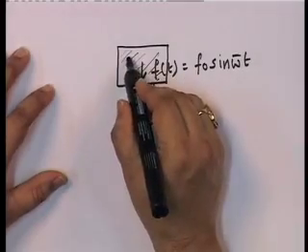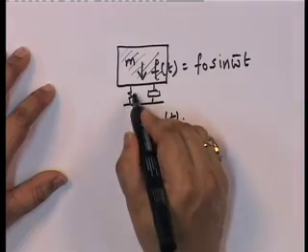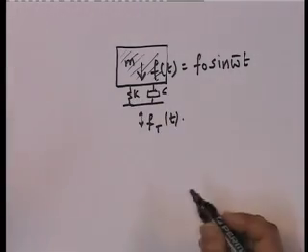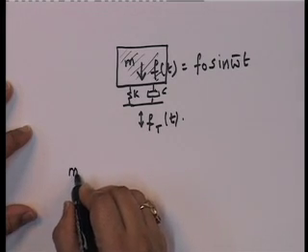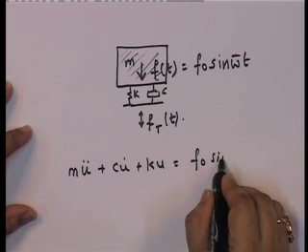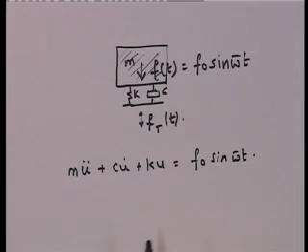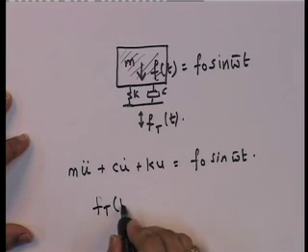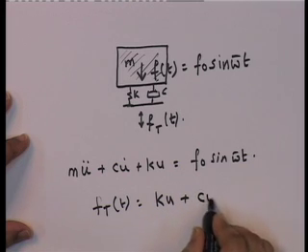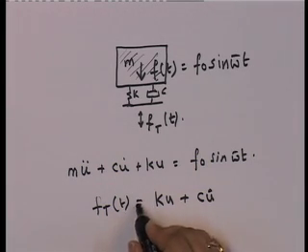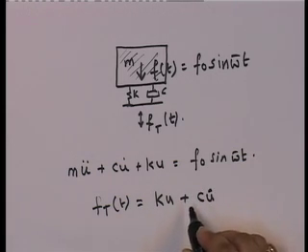If you look at this, this is a machinery block of mass m. It has k and c, a spring and a dashpot connected to the floor. So, this problem is nothing but m u double dot plus c u dot plus k u equal to F0 sin omega bar t. This is a single degree of freedom problem. Now, the question is, what is the transmitted force? The transmitted force is nothing but k u plus c u dot, nothing else. So now the question becomes, what is k u plus c u dot equal to? That is all I need to do.